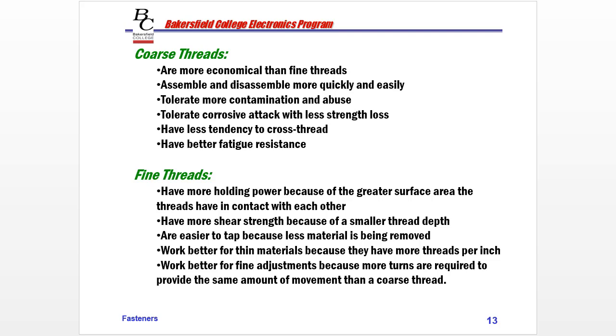They also are better for fine adjustments because more turns are required to provide the same amount of movement than a coarse thread. So we can look at the coarse thread advantages, and those actually are disadvantages of the fine threads, and vice versa.